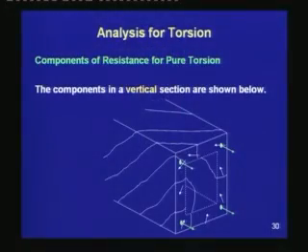The interior of the beam does not carry substantial stress to resist the torsion. If we look into the truss mechanism, we can neglect the concrete material inside and just consider the shell outside the interior region, and this part of the member actually resists the torsion.